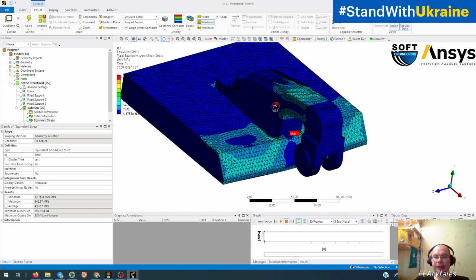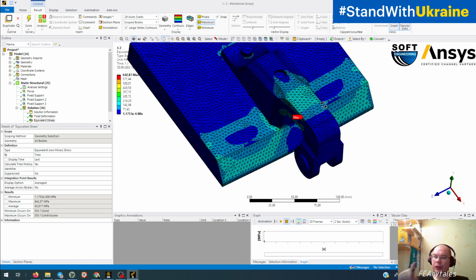So in linear behavior we have some points where stresses must be infinite. Because we solve it not analytically but numerically with a finite element mesh, we can't obtain infinite results, but we will obtain a big range of stress, and it will be much bigger if we make a smaller mesh.